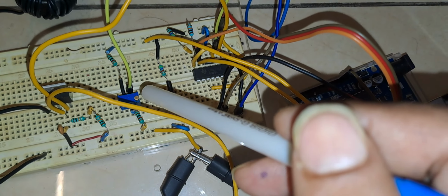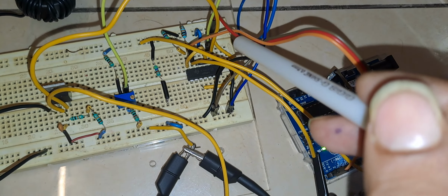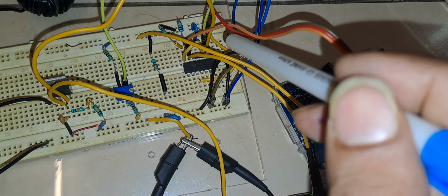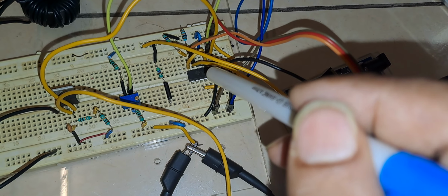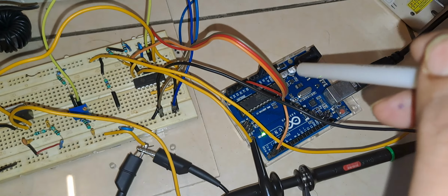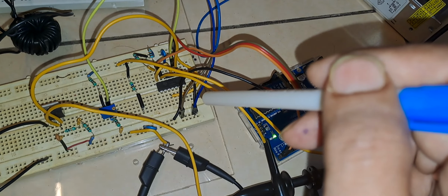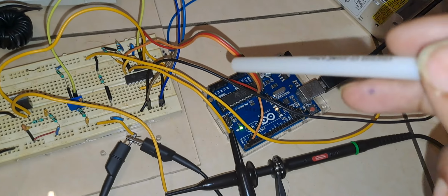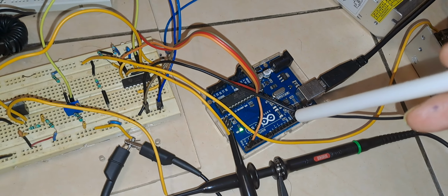This reference voltage we need to set for proper data reception. The output of this first comparator is inverted. I am sorry, it is not optically inverted, it is just inverted. The inverted data is again fed to another comparator here and it is rectified. Finally, the correct data is fed to Arduino Uno. I am going to explain this comparator block very clearly in the circuit diagram. It will be very clear. This comparator is IC LM339. The final received data at the Arduino Uno is fed to the computer console.